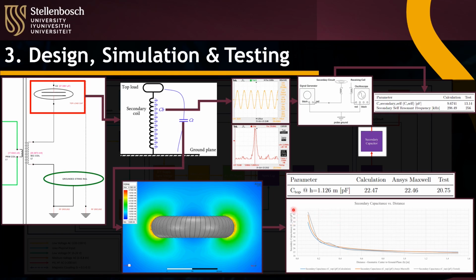Tests, simulations, and calculations were also conducted on the change of capacitance versus the distance from a ground plane. Capacitance in the secondary also occurs between the windings as well as accumulated in the top load. The resonance test was then conducted to calculate the winding capacitance.